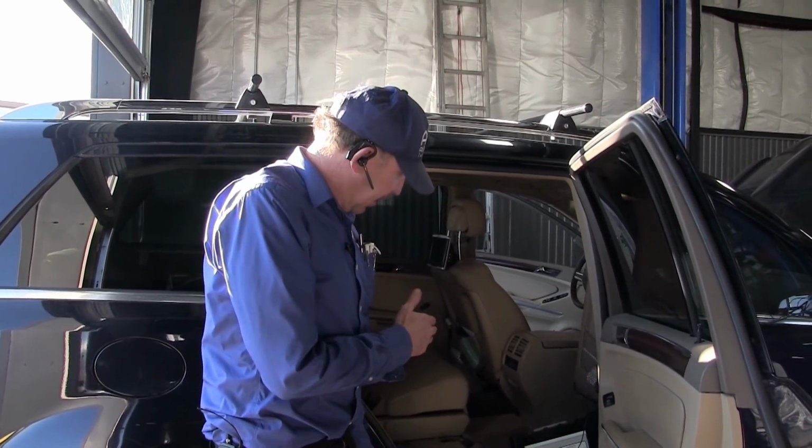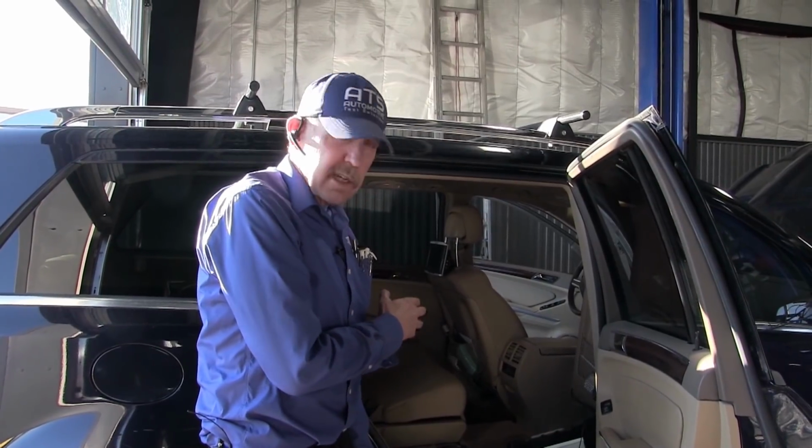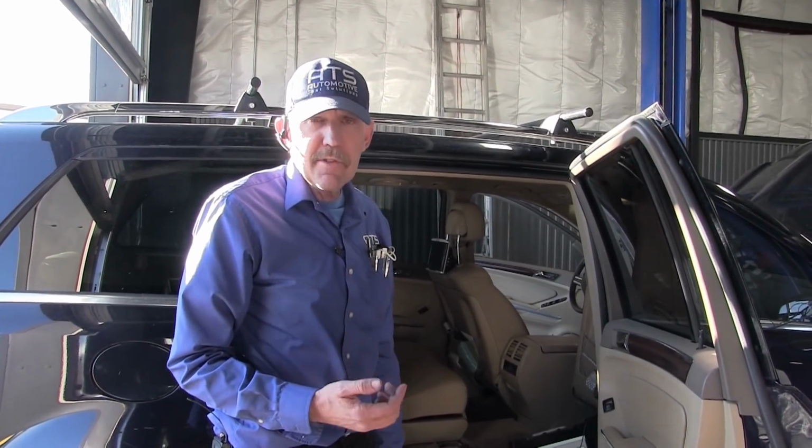Okay, guys, I found the pump. It was underneath the passenger side rear seat. In order to access the pump to get an amp clamp and read the power to that pump, I had to remove the seat. Now removing this seat took longer than diagnosing the entire car. That's crazy, but you've got to do it, because without the data from that amp clamp, I cannot find what's wrong with the vehicle.